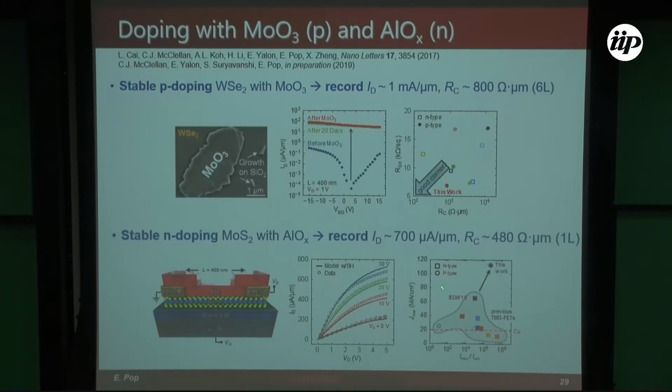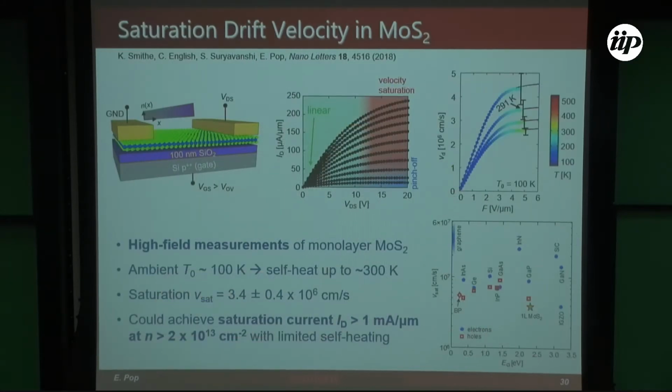In fact, we looked at the real current density, megaamps per square centimeter. This is the data that we found in literature, including ours from the previous devices. And now we're up here, we're actually pushing over 100 megaamps per square centimeter through a 3-atom thick material. Most metals like copper will electromigrate and break down at about those kinds of current levels. So this is actually pretty good. It's good news, I think. Maybe not the most industrially compatible way to dope things, but I hope I've convinced you that doping is extremely important, and to move this forward, we have to take it seriously.